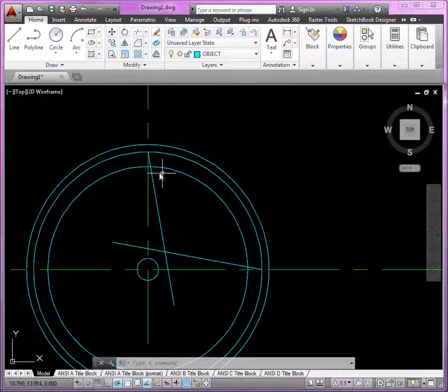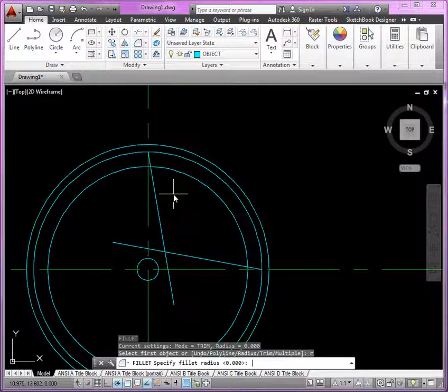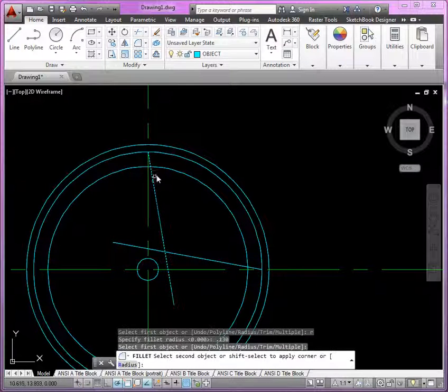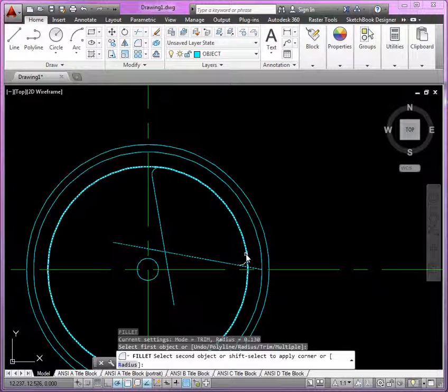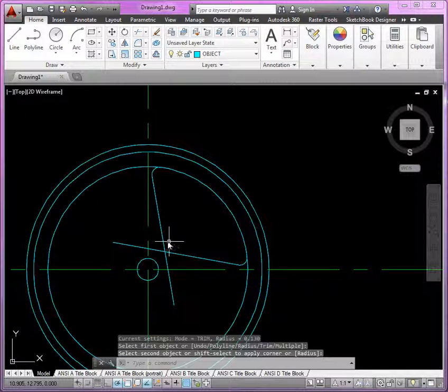And as we mirror this, once we have it trimmed off, we'll be able to complete the interior of the part. So what we have here is average or typical 0.130 radii. So if I do the fillet, F fillet, and R for radius, we're going to do that at 0.130. Okay, and we'll go ahead and select our edges there. And you'll notice that this radius here is 0.250.